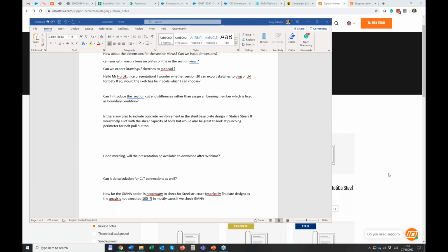So in effect, it doesn't matter which kind of material you are using. The applied forces are distributed right into the connection elements like bolts or welds. So you get a slightly conservative result, but you can check your members, the timber members, on your own, and then apply the material properties. Okay, very good.